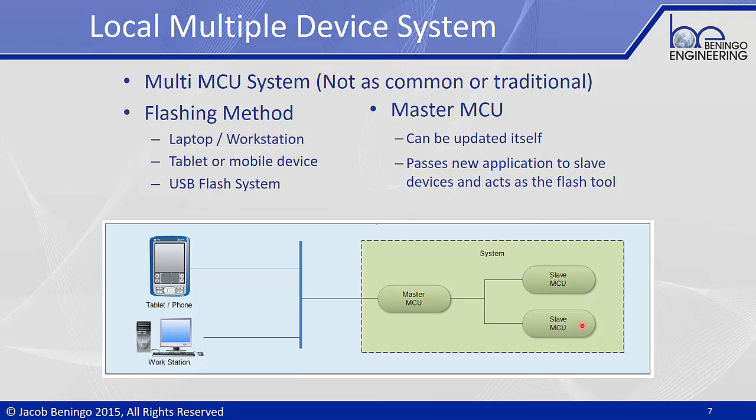This is a little bit less common of an architecture, but you would potentially see this in some type of safety critical system where you have the main microcontroller that's performing the work, and then you have safety microcontrollers watching the behavior of the master to ensure that it's doing what it's supposed to. In that case, we're probably going to have to update firmware on all these different devices, and this is one way in which we can architect our system.